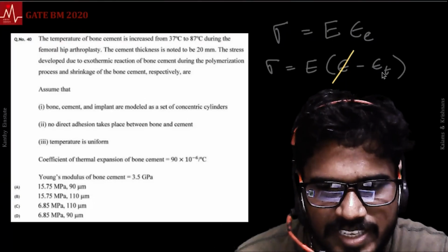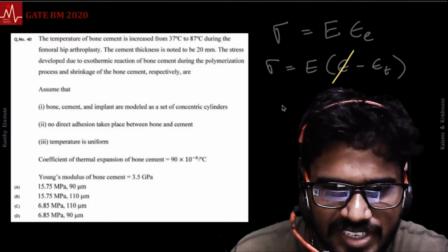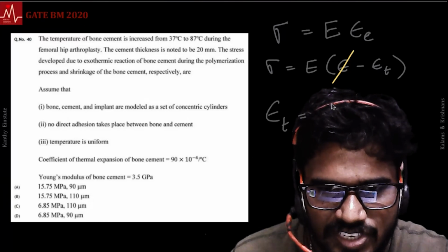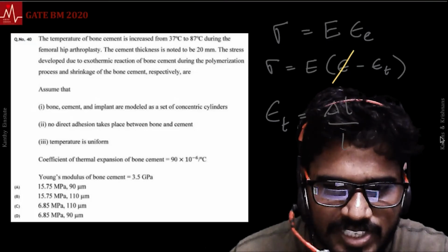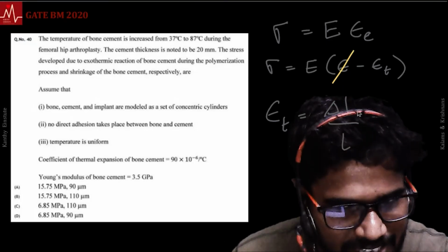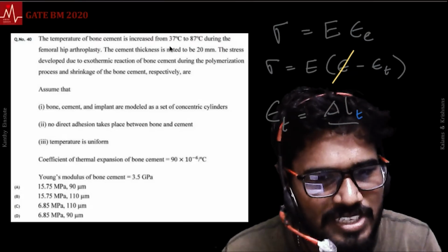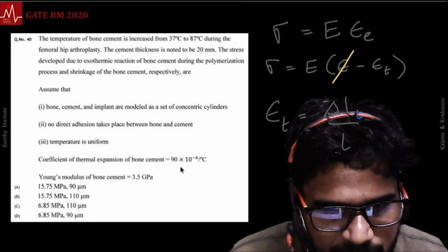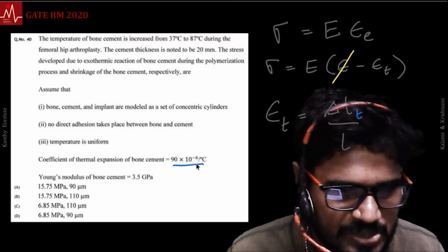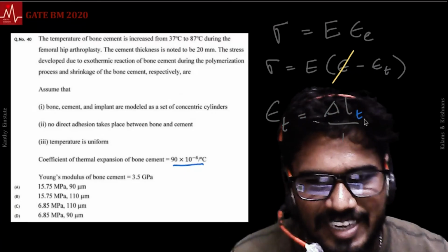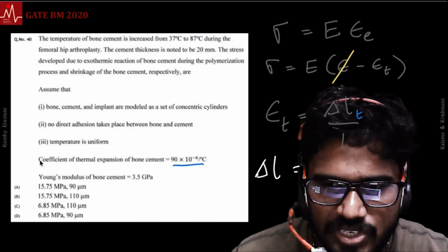I think the thermal strain is fairly easy, I suppose. By definition, strain is change in length by original length. We are talking about the specific change of interest here, the thermal change in length. If you know the temperature difference, the thermal expansion coefficient, linear thermal expansion coefficient, area expansion coefficient, or volume expansion coefficient, whichever one is given, calculate delta L. Call this coefficient alpha.